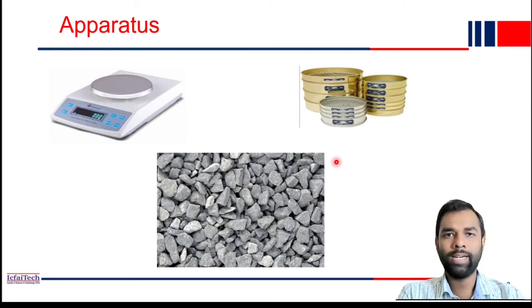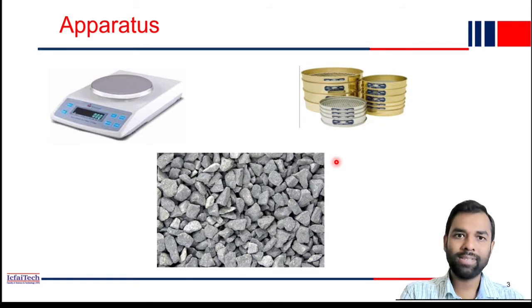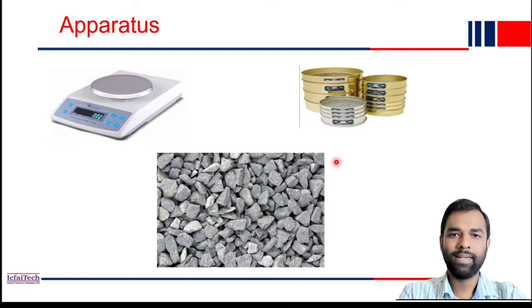At the top will be 20 mm, then we'll use 12.5 mm, then 10 mm, then 6.3 and 4.0, like that. We'll stack all the sieves, and then we'll perform our experiment.